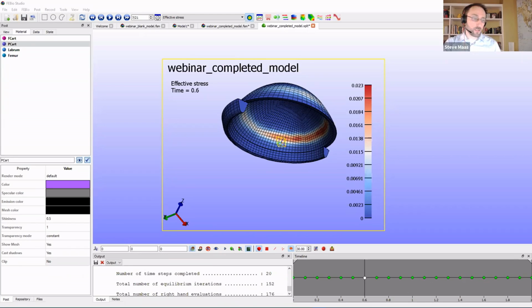So this user asks, is it possible to modify the FEBio input file so that a specific subset of results are automatically written into a text file after the simulation is over? So you can write data directly to a text file, and you can even define which element sets or node sets that you want that data for.